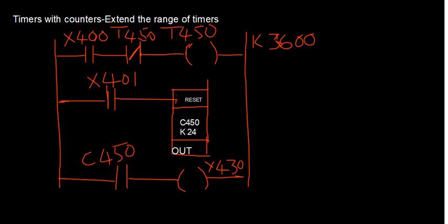Let us say, for example, with a count of FF you get a delay of 2 seconds. If you want more delay than 2 seconds, then with that particular count it is not possible to realize that delay. So what would you do is, you will use a loop inside the loop technique. You will have an external loop and an internal loop.